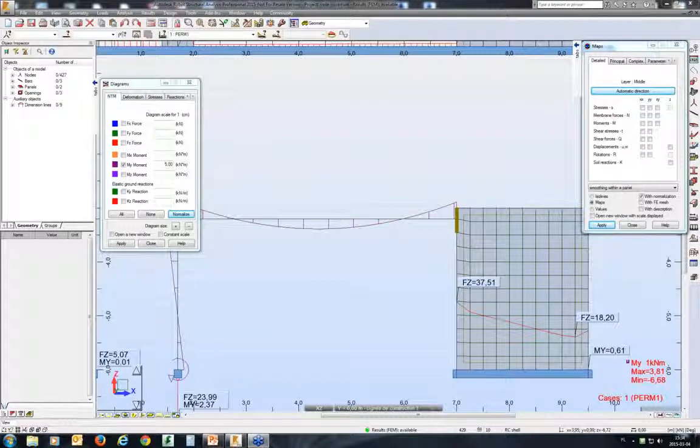I would do this only in the situation when I want to use this option, rather than set it as default and then check where these kinematic constraints were generated and what is the effect of them. So only in controlled situations, when I want them to be defined. So deliberately I will mesh one panel and a second panel with different parameters. I know that the mesh is incoherent at the edges, and I know that I want these kinematic constraints to be generated in this location, but only in this situation. That would be my option.